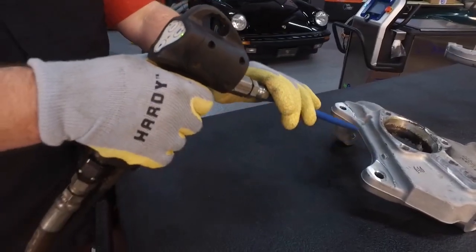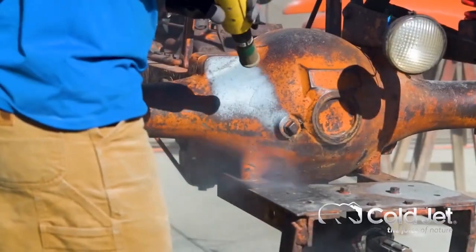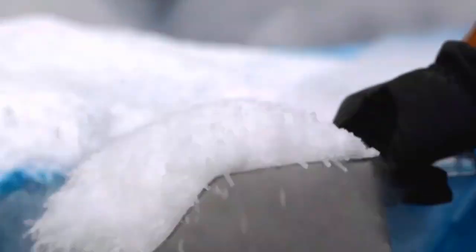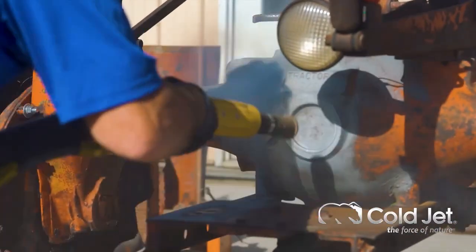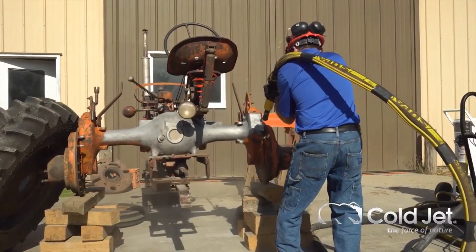How does dry ice blasting actually work? Dry ice blasting works in three main ways. First of all is the kinetic energy or impact. We're taking, in most cases, rice-sized particles of dry ice. We may break those down into smaller particles depending on the application, but then we're accelerating them at anywhere from 600 to 1,200 feet per second upon impact to that surface.